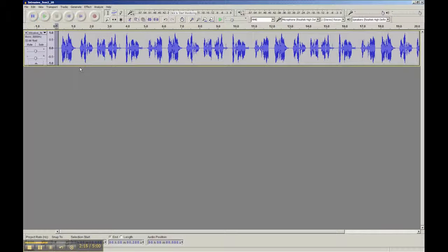So this file, we're going to now attenuate, because the EMU likes to analyze the original and the echo or delay file whenever the echo file is 6 dB lower or more, because otherwise it thinks that the echo delay is really double talk. In other words, another person talking rather than the echo.